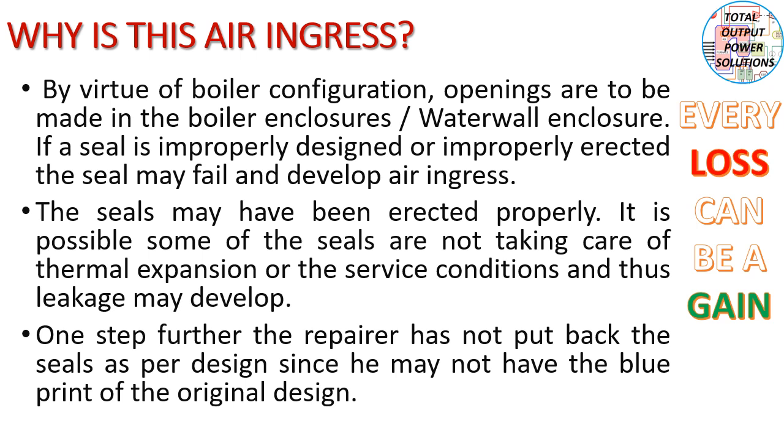Now, why is there air ingress? By virtue of boiler configuration, openings are to be made in the boiler enclosures or water wall enclosures. If a seal is improperly designed or improperly erected, the seal may fail and develop air ingress. The seals may have been erected properly, but it is possible that some of the seals are not taking care of thermal expansion or the service conditions, and thus leakage may develop. One step further, the repairer has not put back the seals as per design, since he may not have the blueprint of the original design.